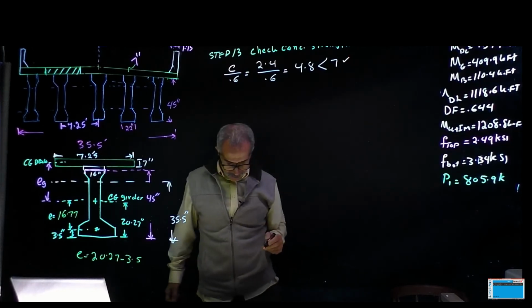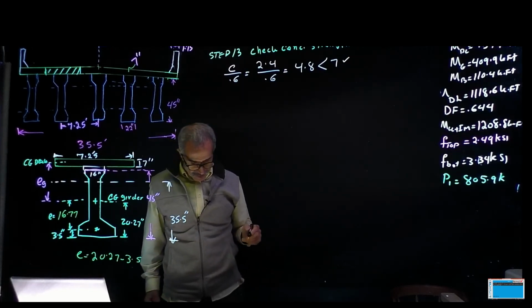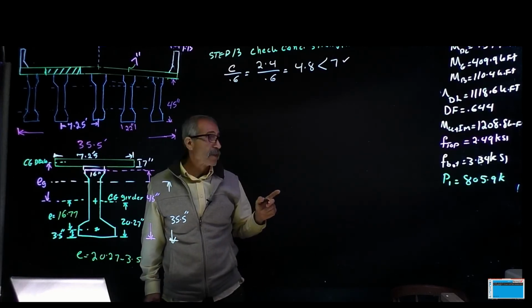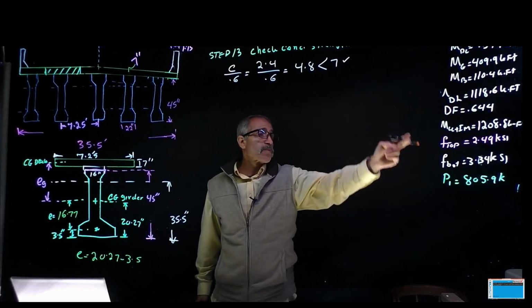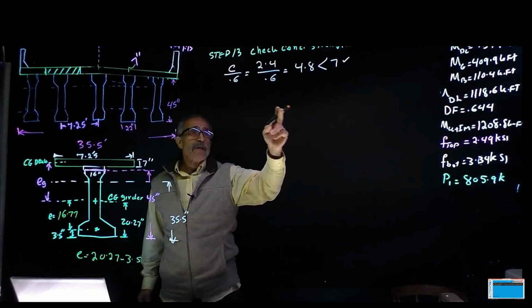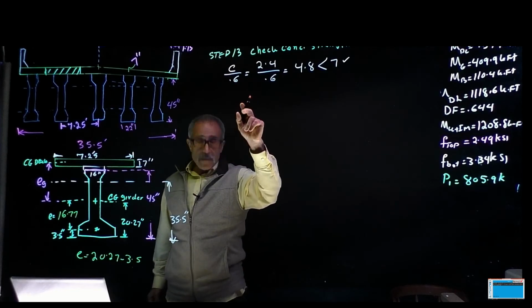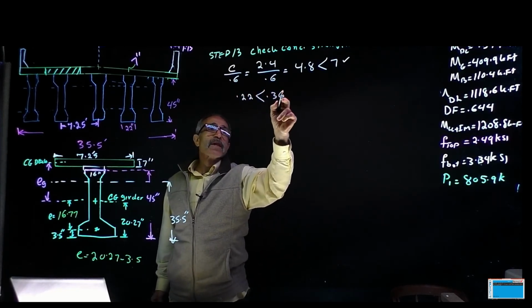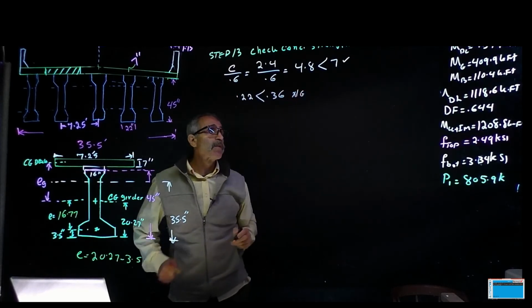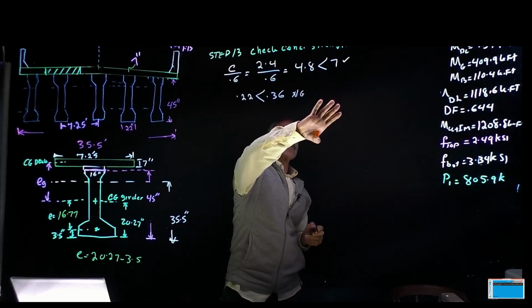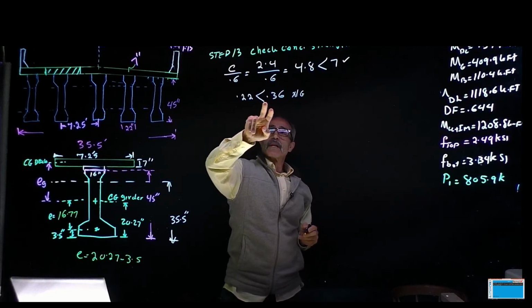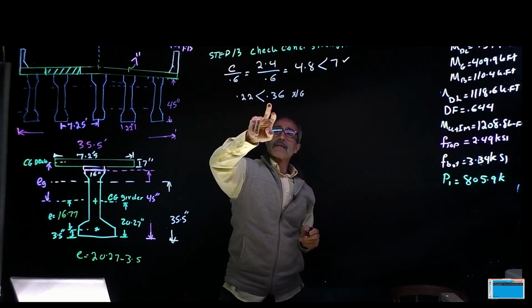And let's go ahead and check the stress limits. I erased it, the tension limit was 0.36. Remember I said it was high. So now 0.22, which we know is less than 0.36. So this is no good. Remember, in the previous step, I just erased the board, we said the tension was 0.36. And this is less than that, it's no good.